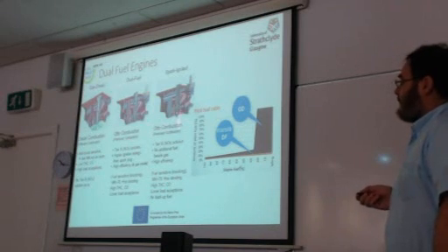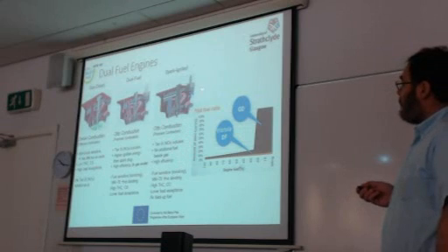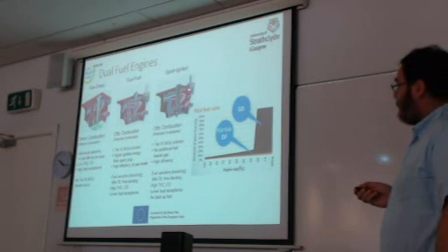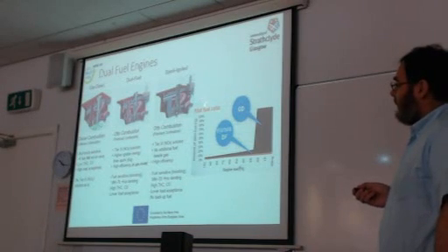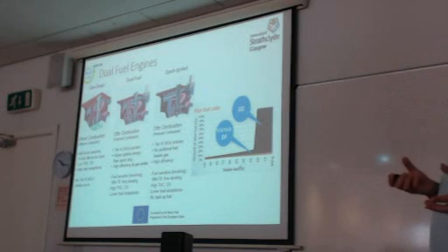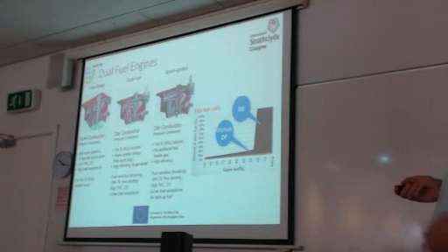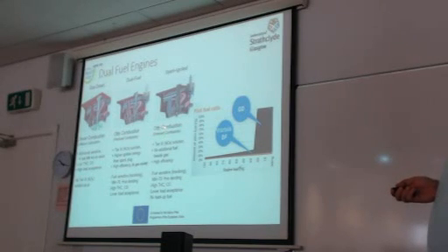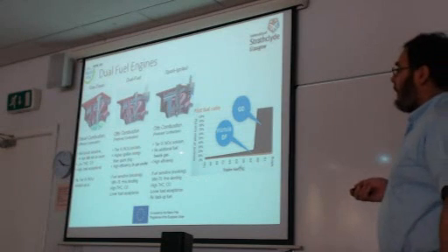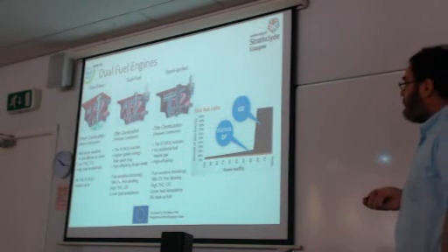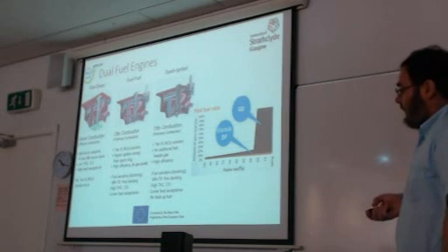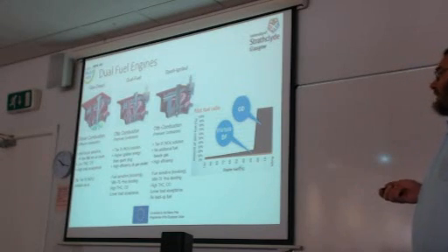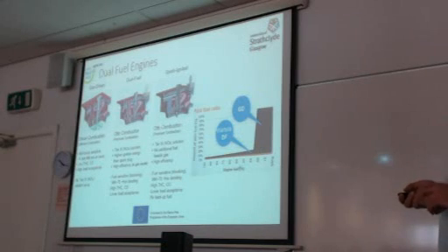And then the last category, the gas spark ignited engines, where a spark plug should be installed in the cylinder head. Of course, in this case, we are talking about premixed combustion. So the gaseous fuel, natural gas, is injected again in the port, and then we have injection and compression. At the end of the compression, a premixed mixture of natural gas and air exists within the combustion chamber, and then a spark can initiate the combustion. So again, as the engine operates with premixed combustion, which means lower pressures, the NOx is low, which means that the engine can comply with Tier 3 levels.